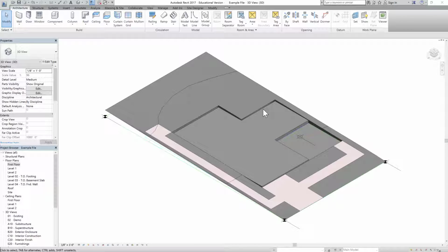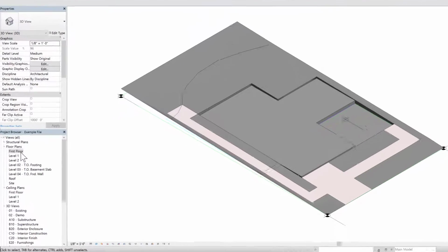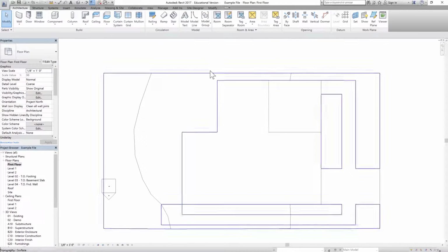So a floor that has a concrete slab and a floor finish on top of that, and then we can insert that. So we'll use the second method. To create a floor, let's go to first floor because that's the level we'll be creating.